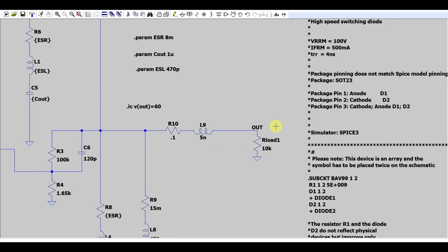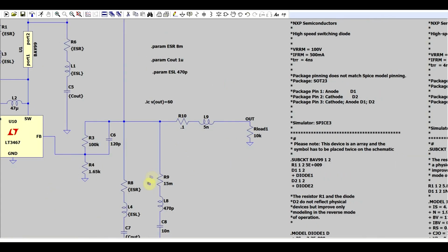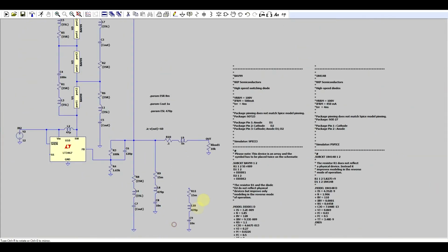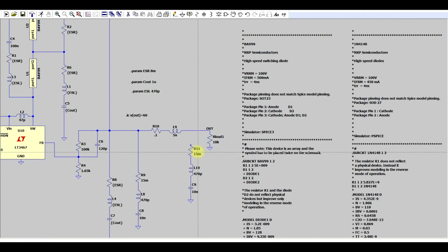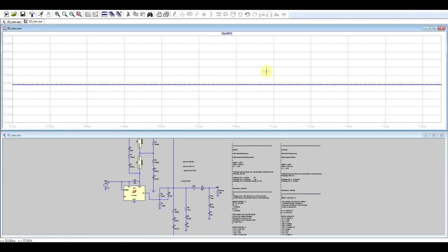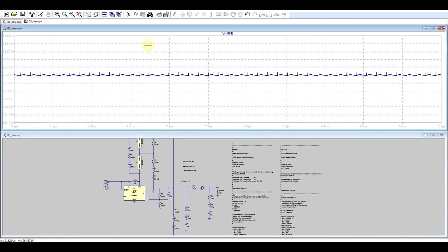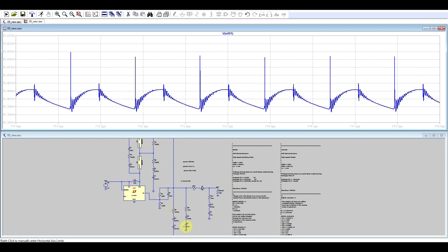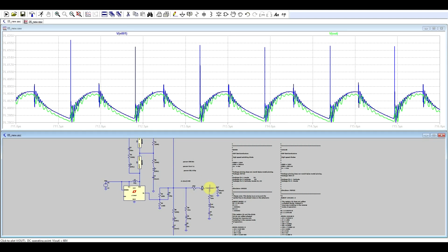Now it's common practice for every sort of load that you have on your board to have a local decoupling capacitor. So if we simply take this 10 nanofarad capacitor and also add it as a decoupling capacitor close to your actual load, then we can see an interesting phenomenon going on. So this is how the noise looks like at the output of the supply when an extra 10 nanofarad capacitor is added, and this is what it will look like at the actual load.